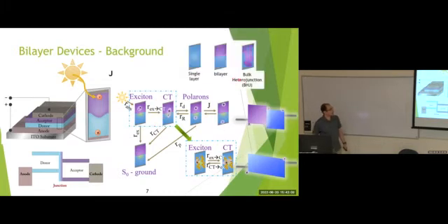And in modern devices, we are using the architecture of bulk heterojunction or BHJ, where we mix together both active layers in order to get larger areas of interface, and also to suppress the exciton decay, because wherever we absorb light, there will always be an interface nearby that the exciton can diffuse to before decaying.